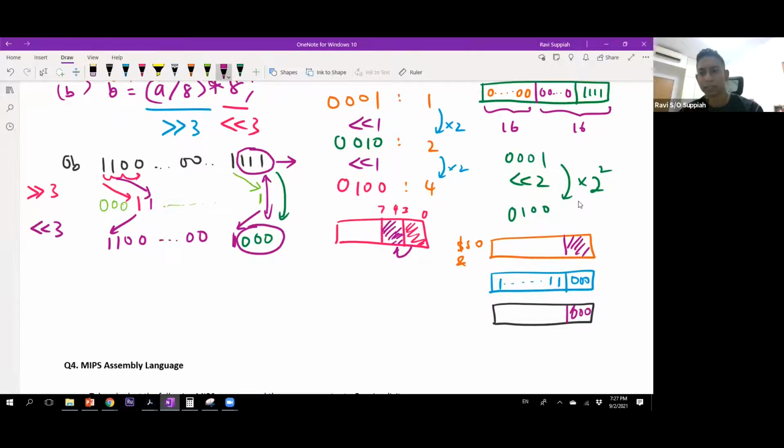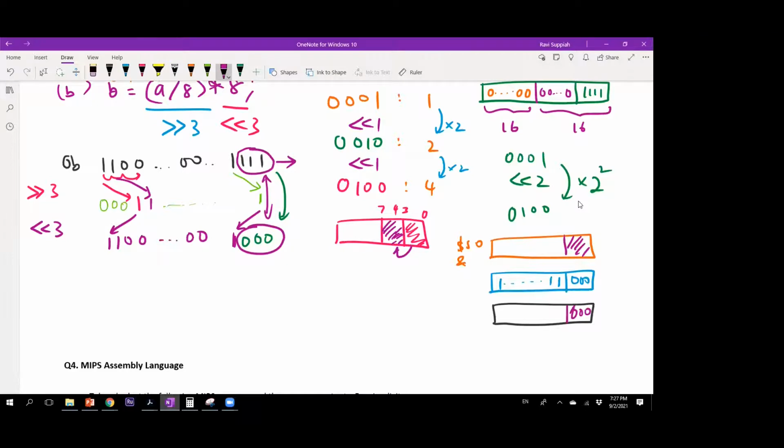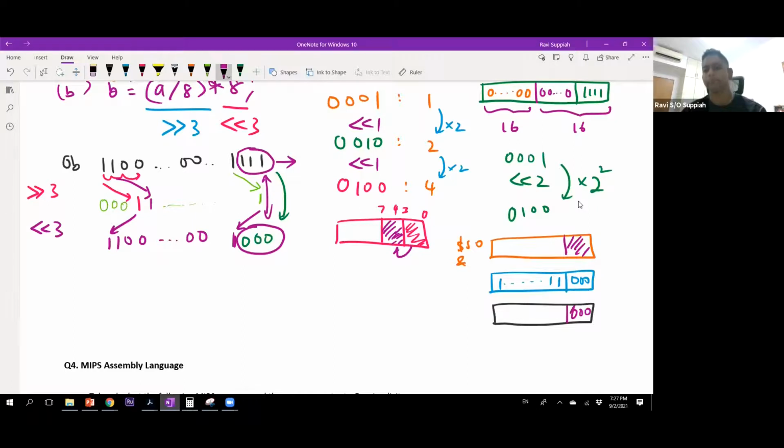That's the bit masking technique, so we have seen this before. Now, this idea, of course, is correct. There's nothing wrong with the idea. The issue is why we can't write an instruction like this. Technically, if I were to write an instruction with S0, this value here will be represented as 0xFFFFFFF8, and put into S1.